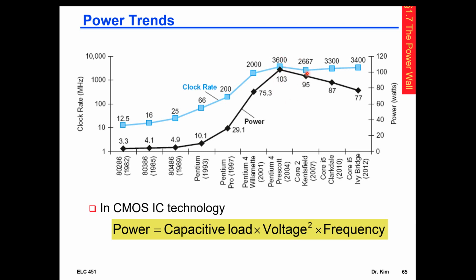So we had done everything we could here with power supply, and now we have the frequency. Well, the frequency is constant. And by putting more devices, we do increase this capacitive load, but they are smaller. The geometries are getting smaller. So even though we're putting more, the fact that they are smaller tends to keep this constant as well, and maybe make it a little bit lower. So that's where this lower trend comes in. So this is a very important and interesting chart.